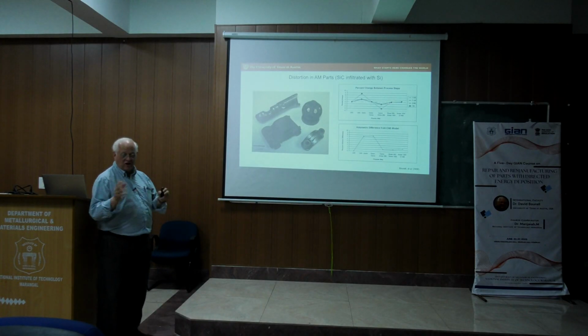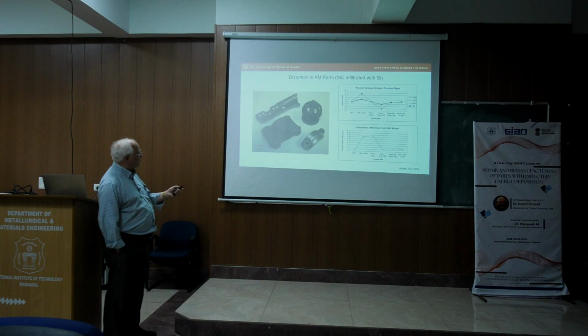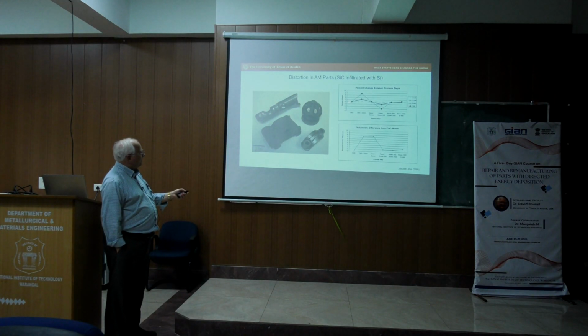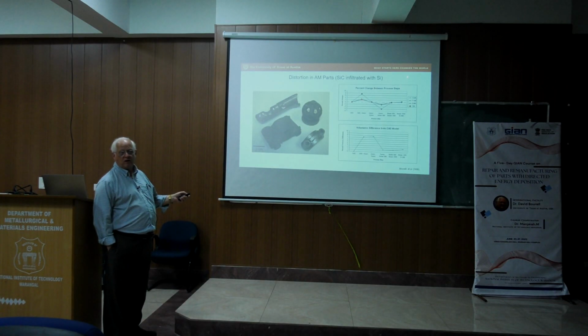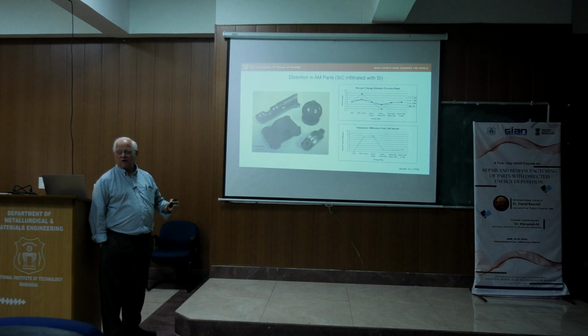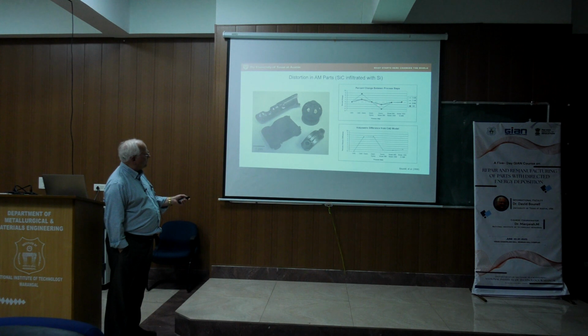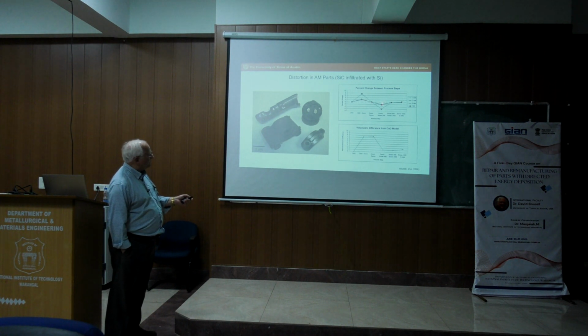But anyways, having said all that, now we can go fairly quickly through this. With the solid modeling, there's about a 2% expansion going to the green part. So the build part is expanding. As we go to infiltrating with epoxy, we get some shrinkage. As we burn off the part, we get more shrinkage. So this is the brown part.